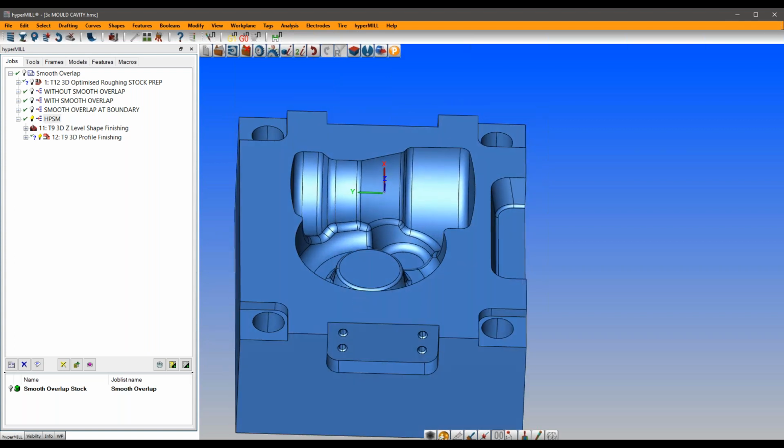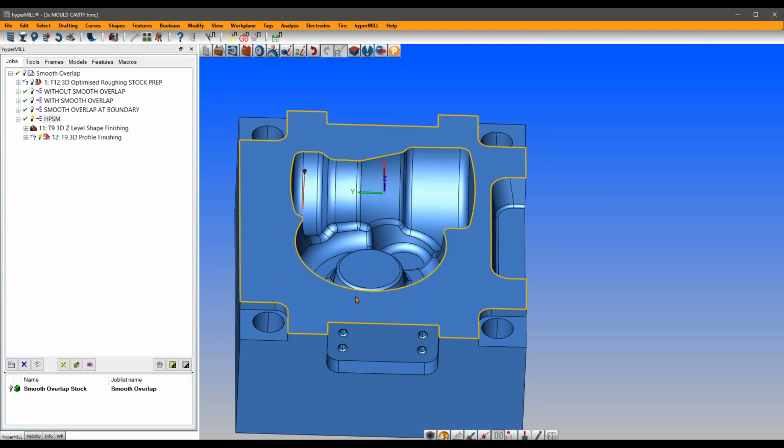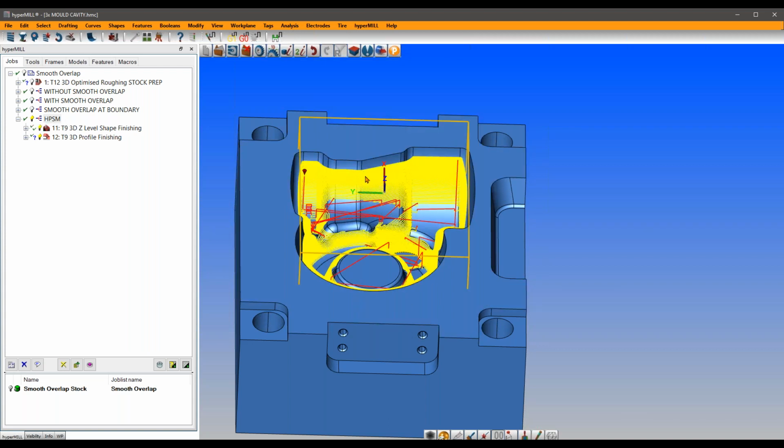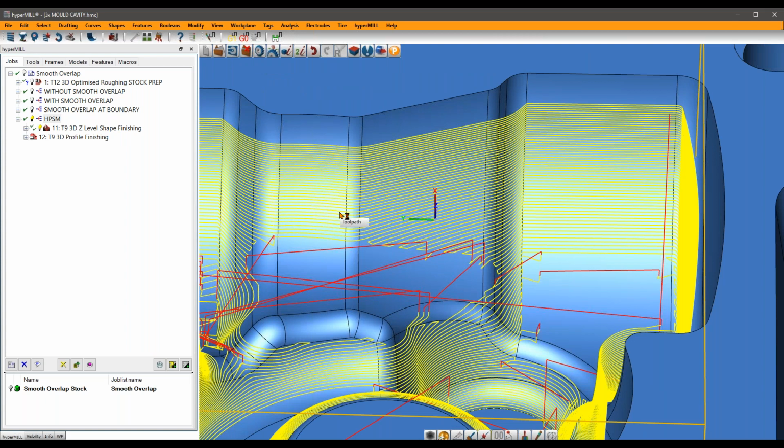Now we're fine machining tolerances like this. It just takes a moment. Now, what we're going to see is a point distribution over these toolpaths, and each one of these points is a line of code on your machine, a coordinate to get to.